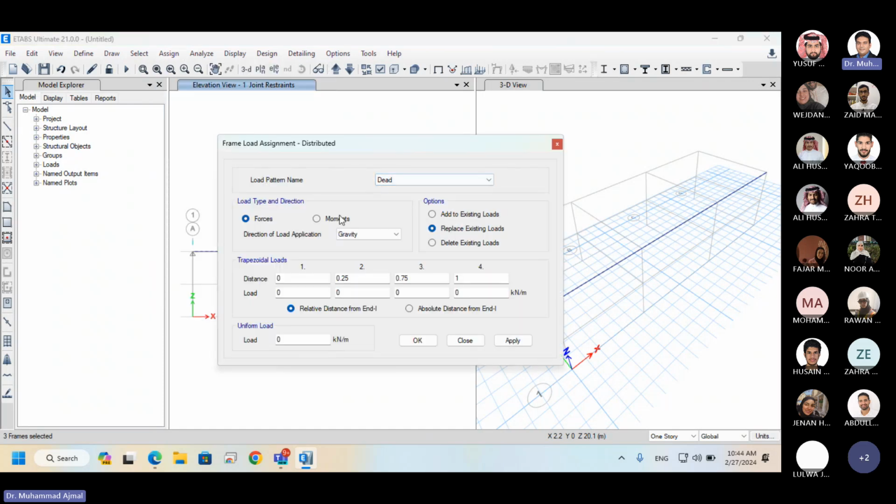When you click on distributed load, a load pattern option comes up here. Now I have to define this option before applying the load. I just came here to show you these options. If you click here, there are only 2 patterns shown currently, dead load and live load. This dead load, shown by default, is to compute the self weight of the structure. It is nothing related to any additional load you want to apply.